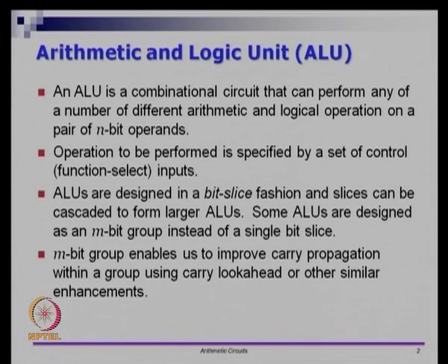Based on the program, you may have operations which say now add these two numbers, subtract these two numbers and so on. Typically you design them using what is called a bit slice fashion. A bit slice fashion for an ALU is one in which you design the circuit for one stage and you just copy that for all the other stages, and that gives you the whole design. For example, when we did the triple carry adder, just the full adder is a slice. So, that is a single slice and I put various slices together and I get the whole circuit.